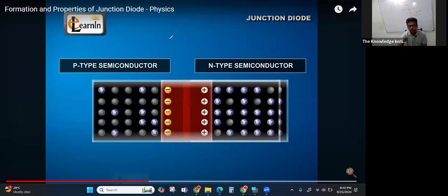Okay, so again, I'll explain now. Due to the diffusion of electrons and holes, there will be a diffusion current in this direction. As electrons diffuse, there will be a depleted region left with donors and acceptors. We know acceptors are negative charges and donors are positive charges, right? As the electrons and holes diffuse, there will be a small built-in electric field in this direction, E.